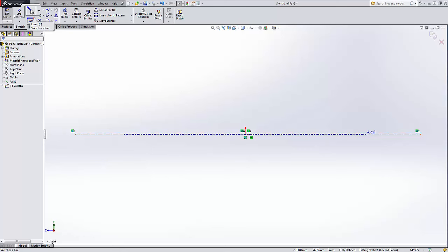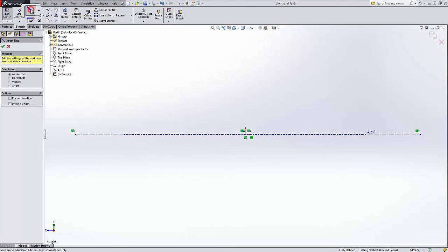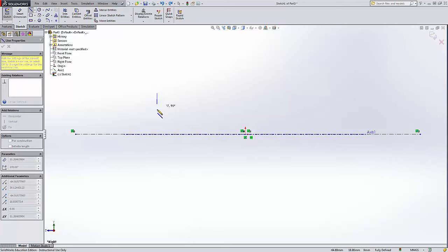I'm going to use common solid lines, and I'm going to start with the undercut that is shown with that 1-inch dimension. Click here, come down here, come over here, and notice I've got a horizontal line that when I get to this point, it indicates a vertical line for the origin.